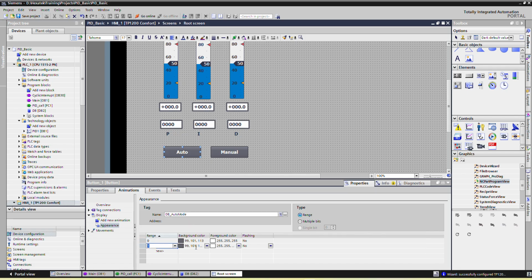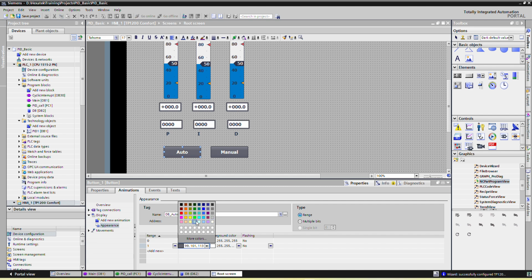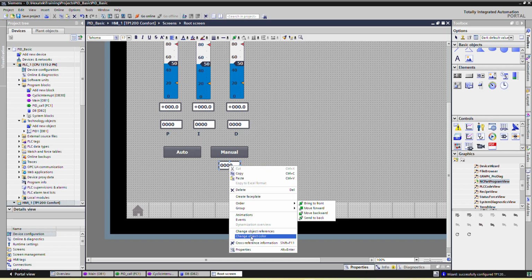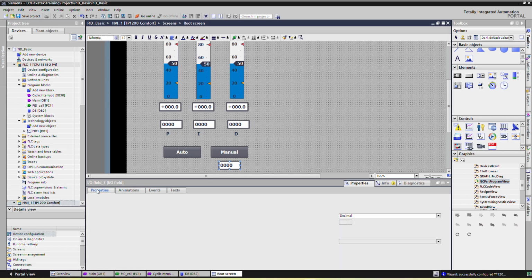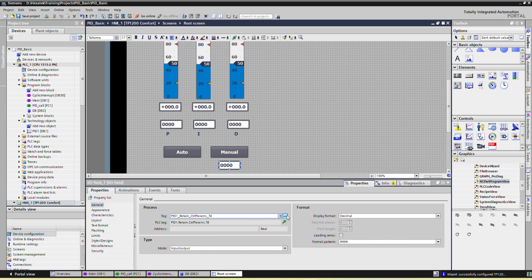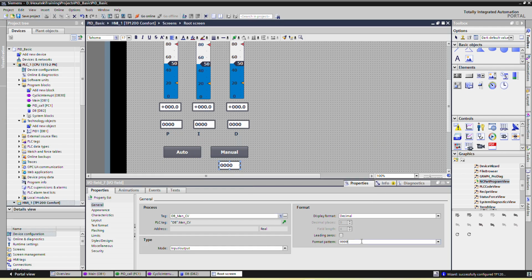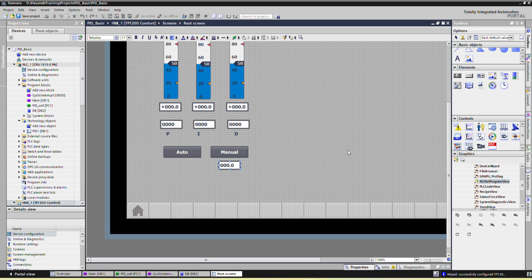Appearance, and to enter manual value also we will give one entry here to put manual value. If PID is in auto mode, we can put manual value from this tag man CV. The value is real. Okay, so now setup is ready to test.